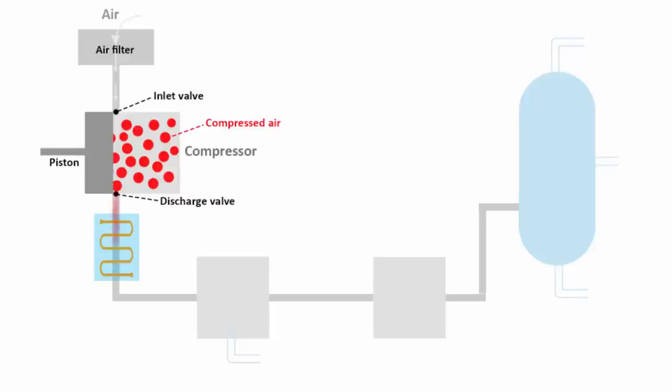One thing that you have to understand is that when air is compressed, it heats up. Because when you pressurize a gas by compressing it into a container, you're putting all those molecules into a smaller volume of space, and you are adding potential energy by the compression. Then when you release that gas back to atmospheric pressure, that energy has to go somewhere. So it's given off in the form of heat. That means the air that is released through the discharge valve is a warm air.